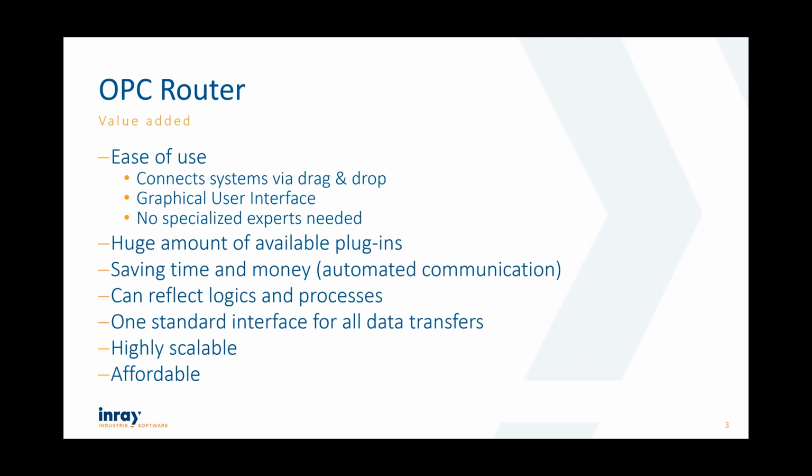What's the value add, especially if you compare it with Kepware? So Kepware is more or less, at least from my perspective, an OPC server. What Kepware does very well is it connects to PLCs and translates all these different PLC protocols like Modbus, Profibus, Profinet, and so on into OPC, into a standard automation protocol.